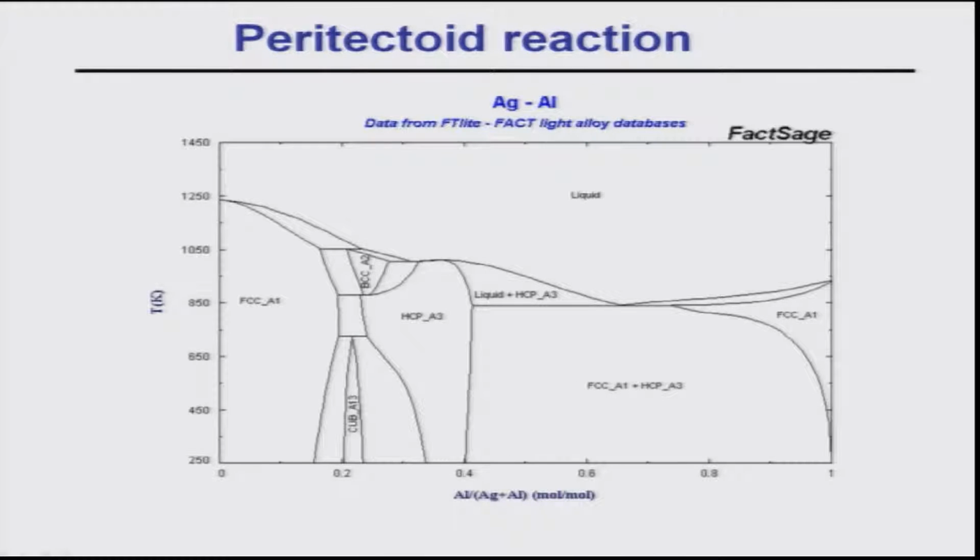Okay, you see here, this is the single phase. This is alpha, this is gamma. So, alpha plus gamma going to beta, correct. You see this is what happens. Not only that, there is another peritectoid reaction which you cannot see here, because there is a phase here, alpha plus something else. I think delta can also lead to formation of gamma. This is the way the reaction happens.